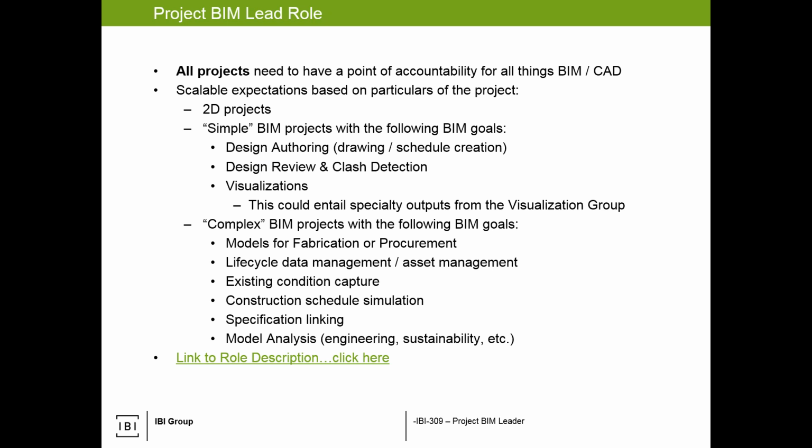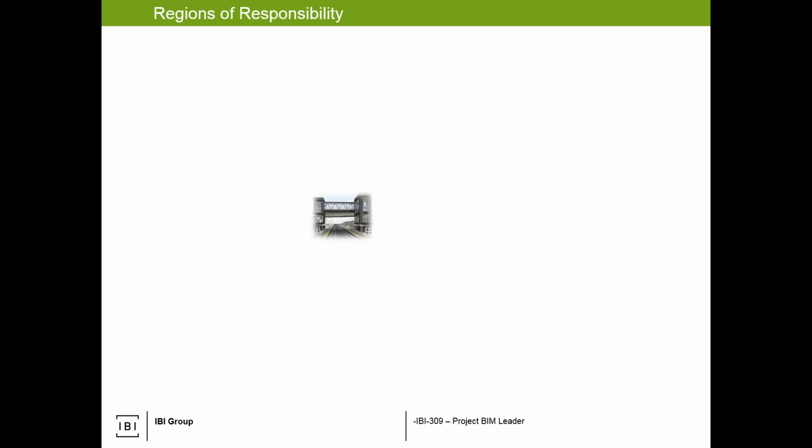Who's going to make sure the data that's going to the fabricator is good enough to be fabricated on? That's a huge question and a huge potential for risk, especially if we're on a DB or a P3 project and we've contracted to say this data will go straight to a fabricator from our design models. That's very risky. So if you do see that in a contract, please pause and let's say, here, are we sure we want to do that? But that bottom half for complex, that's a huge undertaking and it needs to be accounted for.